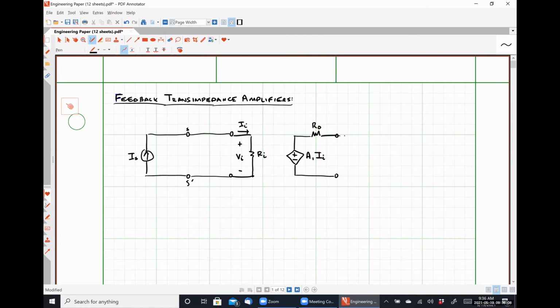And now we're at where our feedback will be connected, which are these terminals. I'm going to call this guy O and O prime. And this is where our output voltage is measured. For our feedback network, we're going to characterize this with a current source here at the input, having a value of K Vout. And port 2 of our feedback network is just going to be an open circuit.